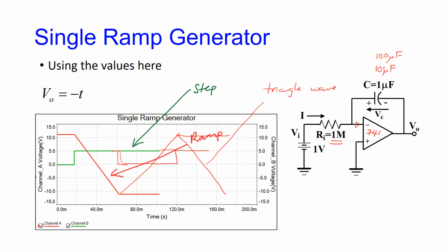And also, if you remember, when we did signals, the Fourier series, you remember that the square waves gave you things like odd harmonics, right? So you had a DC value and you had a perfect square wave, which is a 50% duty cycle, that had odd harmonics.